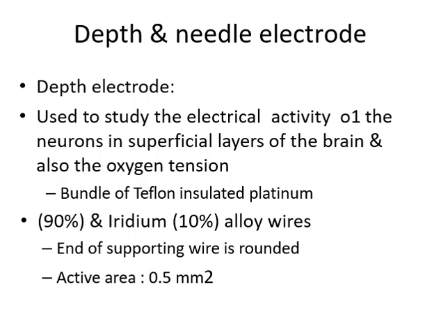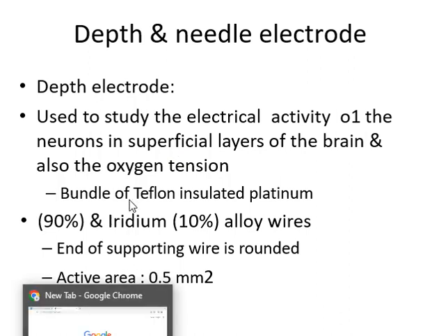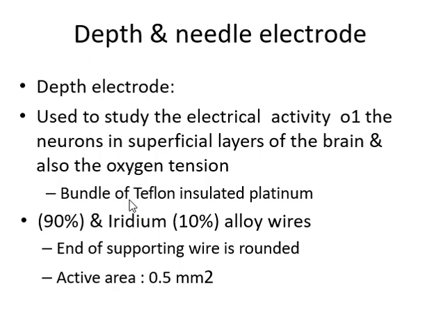Deep electrodes are the major vehicle for collecting microwire recordings while performing intracranial EEG for epilepsy monitoring. Deep electrodes acquired with microwires are referred to as hybrid electrodes. The most commonly used hybrid electrode is the Behnke-Fried electrode, which was first developed by Jens Behnke. This type of electrode has become the most common and major vehicle for human single neuron recording.